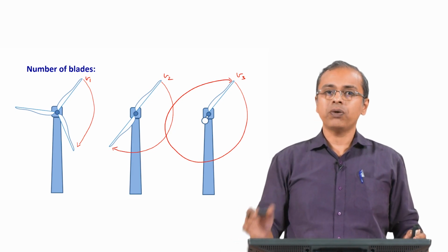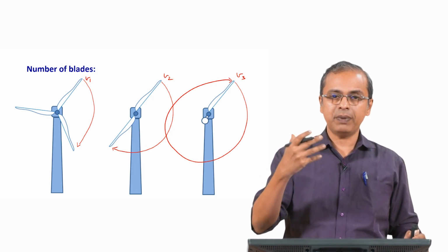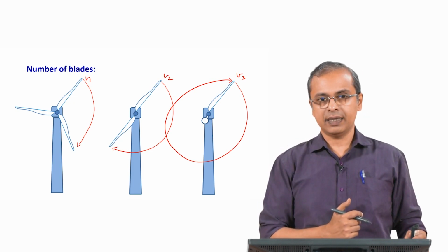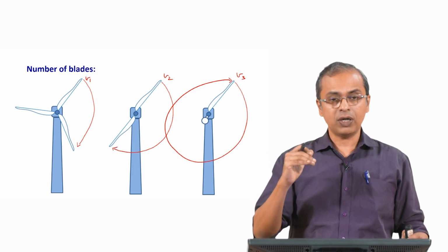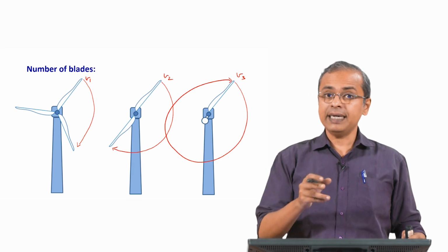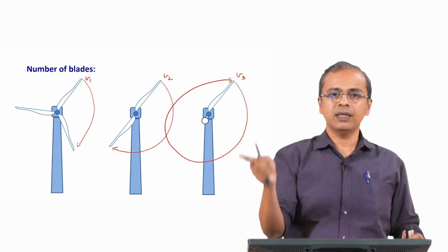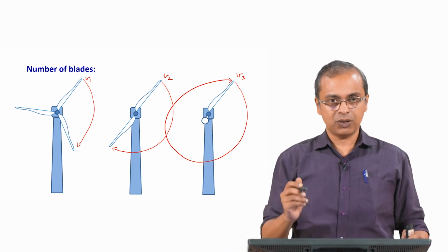speed ratios, and also you have to keep in mind that if you are using this primarily for generating electricity, then having higher RPMs is what is more useful to us. Generally the torque requirement is not as high, whereas the RPM requirement is much higher. And therefore, high tip speed ratios are important because that decides the RPM. The faster the tip is moving, you will have a higher RPM, right. So, generally these designs are based on that thought process.